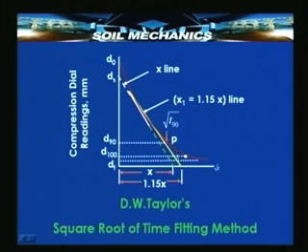And where this line cuts the red curve, you can see that the yellow line is cutting the red line somewhere here, that is the point corresponding to 90% consolidation. And once we know D90, we will know T90 or root of T90 for that matter. Once we know root of T90, we already know there is a relationship between small t and CV.